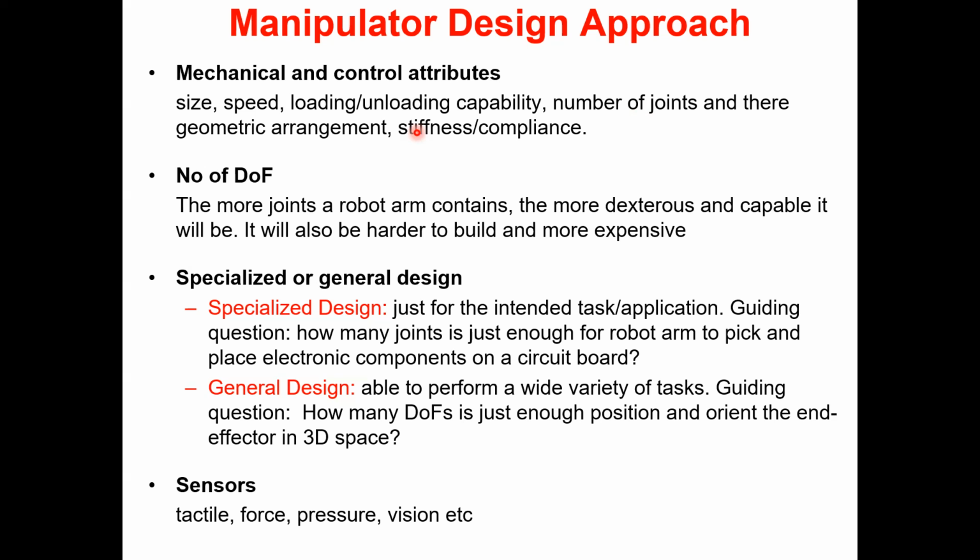So as long as there are no obstacles around, there are no people around, you can have a very stiff manipulator, so that your welding operation, your laser cutting operation will be very accurate. Because if you do laser cutting, you want very straight lines, very accurate positioning, right? And if you want to do welding also, you want to follow the line as precisely as possible. And also, if there's any deviation, quickly recover from that error, right? So you've got to have this high stiffness.